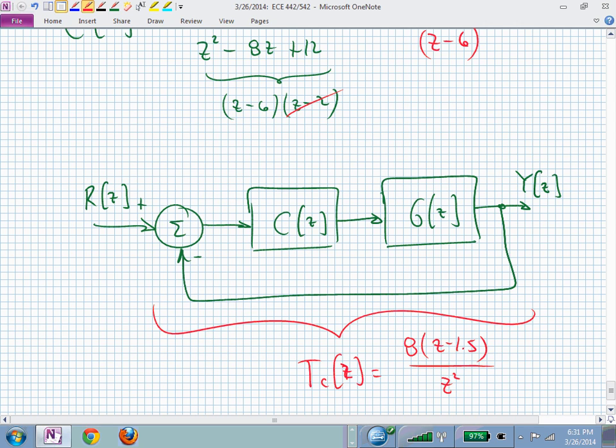And what influences stability in this closed loop system? The feedback has helped us, hasn't it? It's now stabilized. We put an unstable controller together with an unstable plant, fed that back, and we end up with a closed loop system behavior that's actually stable. And it even has a deadbeat response.